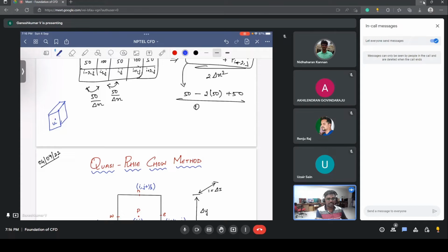If the flow is from right to left, and we are interested in evaluating the value at face w, then what value is required at the node? It goes from east to present, present to west. For pure upwind scheme, you need to go from phi P to phi W. So for the first one, it would be just phi P, right? Is that clear?